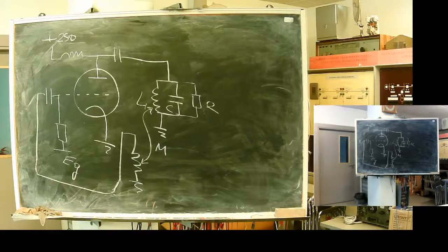Such structures were popular till some 50s. There's a problem. Interturn capacitance limits frequency because a resonance appears in part of the coil. If we make a coil in kind of layers, between layers also occurs capacitance. So within one layer and interlayer capacitance appears its own resonance frequency, and the coil is not working as one. It splits into separate resonance contours. So to prevent it, one of the techniques was to use such kind of winding. It takes a lot of space, but capacitance is much smaller.